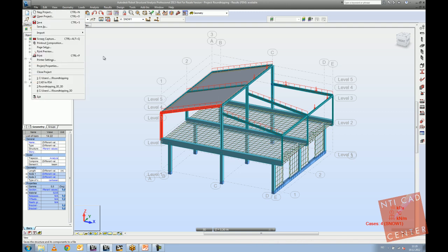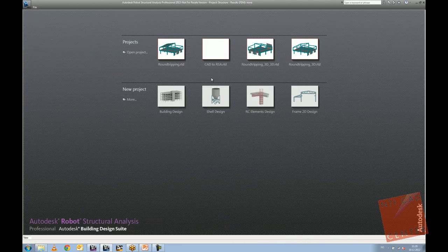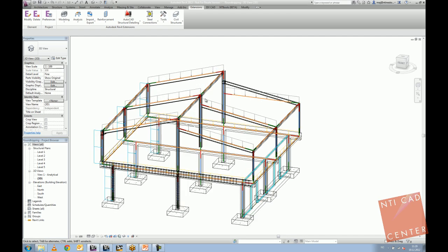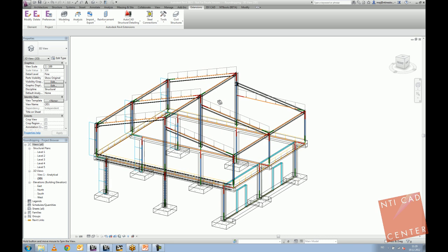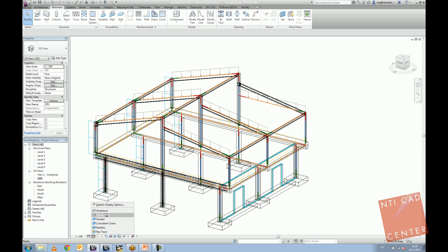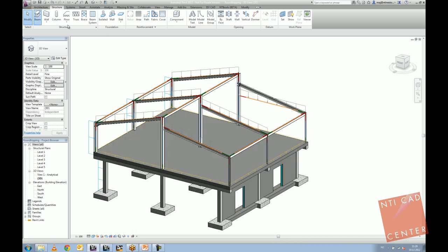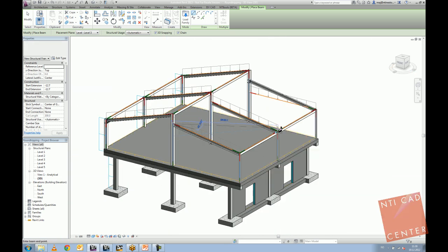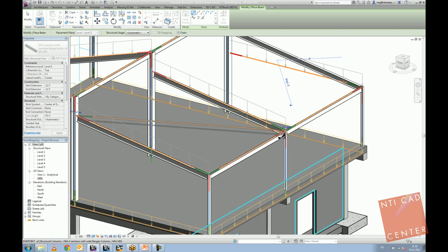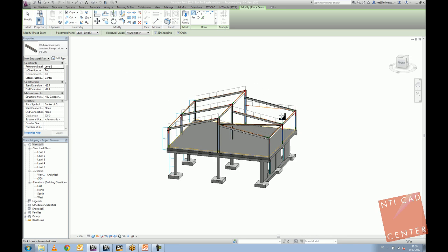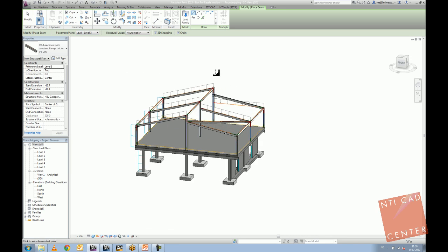I haven't saved the file anywhere, so what I will do, I will just close it now. Go back to Revit, and let's say you've done some modifications. Let's say you actually added some more elements or maybe modified them. Let's try doing something here. So if I go to beam, let's try 3D snapping. I hope I will catch it in the right place somewhere. Let's say I have added one beam, just theoretically speaking. So I have updated my model.